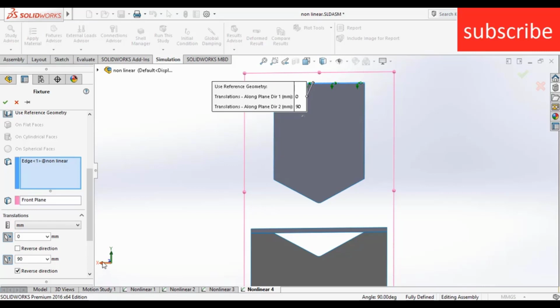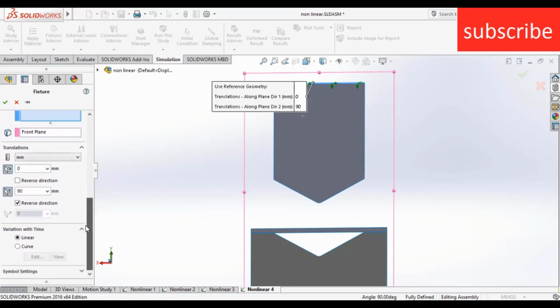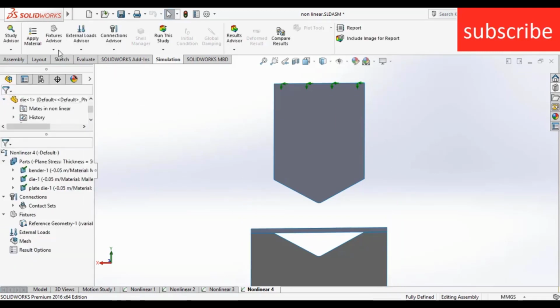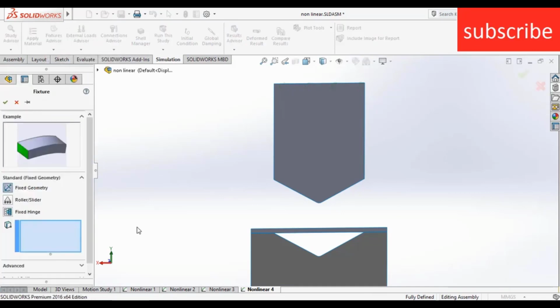Okay, as you can see, it is x axis, and I click on x-axis 0, and for y-axis I just click on reverse direction, so it goes 90 mm downwards. Okay, click OK. Now here go to fixed geometry, click on fixed geometry.